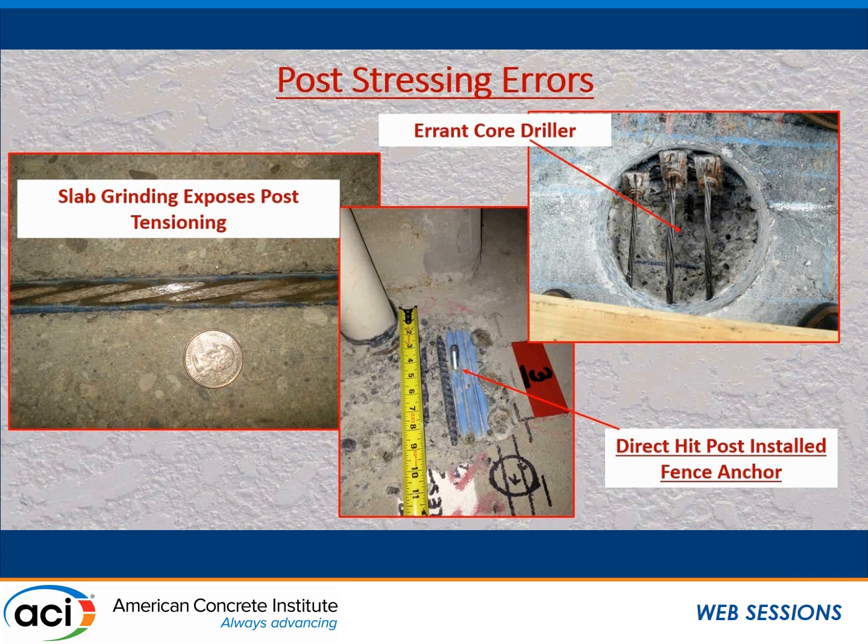The photograph in the middle there is, as Tony would say, one of life's little disappointments. Some knucklehead comes in to put in a chain link fence, doesn't even begin to consider that it's a post-tension slab, and he could have hit it more dead center. And so then that leads to an investigation, and then you find more problems because these things have occurred more often. And you know, those things are sometimes simply remedied by the use of a good quality GPR technician or company.